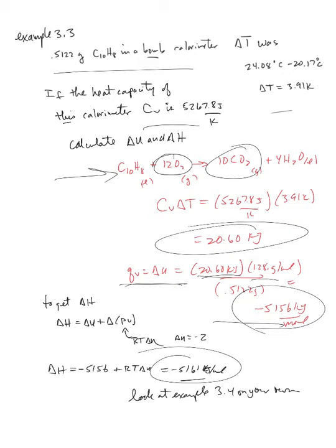Why is that? I have some notes here. Notice that delta U's and delta H's are virtually the same in constant pressure environments or constant volume environments. Q, however, is a little bit different because it is path dependent. We ignored heat capacities of the products and any excess oxygen. Those aren't really big errors. Note that you get a little bit more heat out of the constant pressure process because the atmosphere is doing some work on the system.